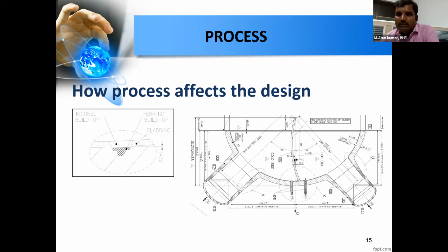So we go for ferritic steels and we are going for cladding. What happens when we go for cladding? Sir, here I have shown one photograph of a component in which we have done cladding on the material. What happens? We are getting some defects in UT or RT in the interface between this ferritic material and the cladded material, that is austenitic stainless steel.